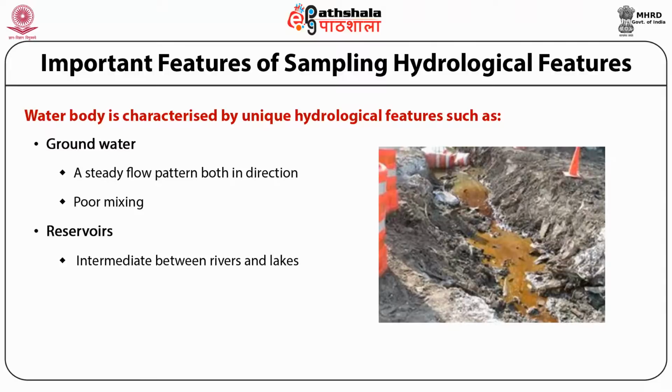The hydrodynamic characteristics of each type of water body are highly dependent on the size of the water body, climatic condition, and the drainage pattern associated with it. Groundwater greatly depends on the recharge regime, that is infiltration through the unsaturated aquifer zone that allows renewal of the groundwater.